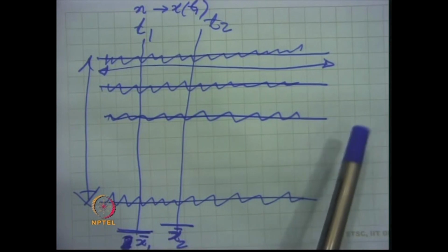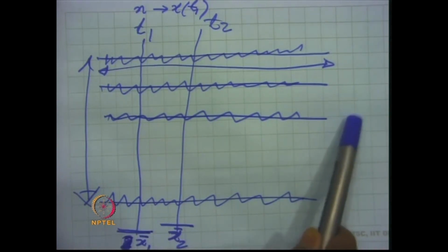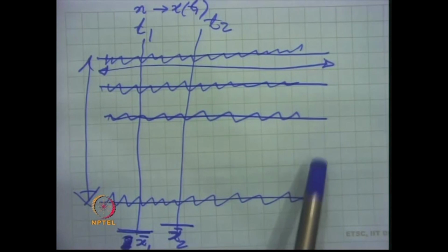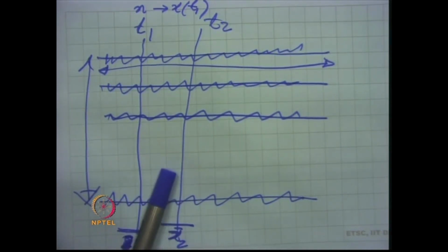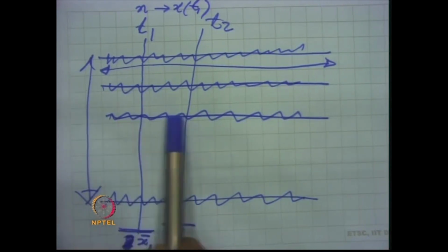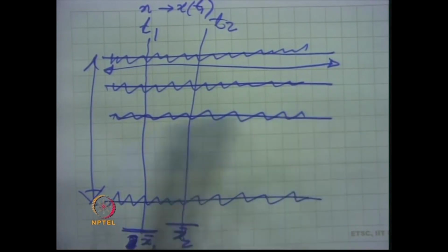So, if this mean square value is same for all the samples and is equal to the ensemble mean square value, then we call the process to be an ergodic process. Now, in that assumption, it is implicit that a single time history sample taken out of the ensemble represents the mean square characteristics of the entire system.